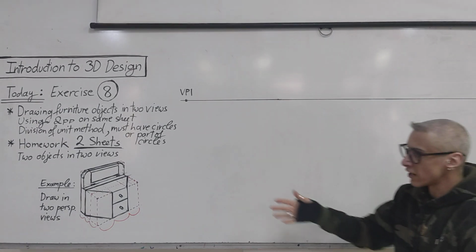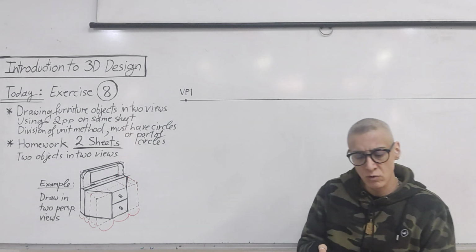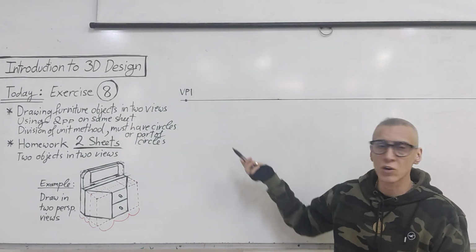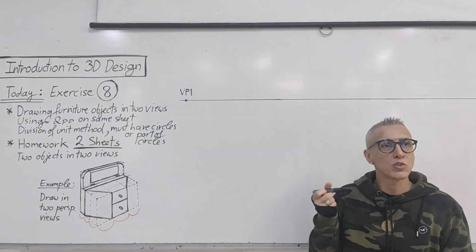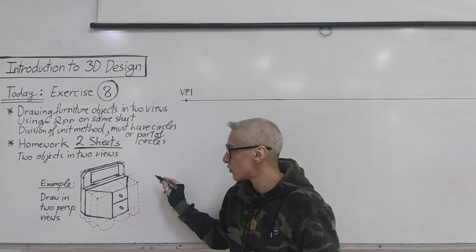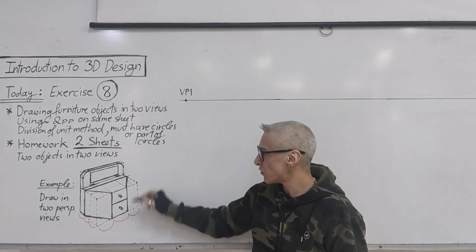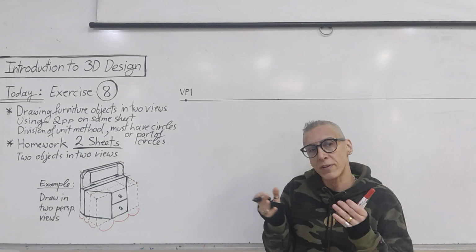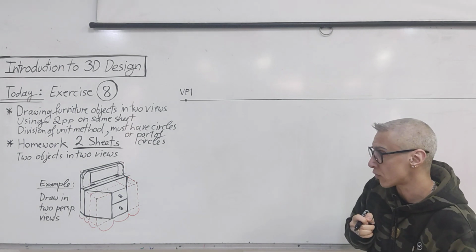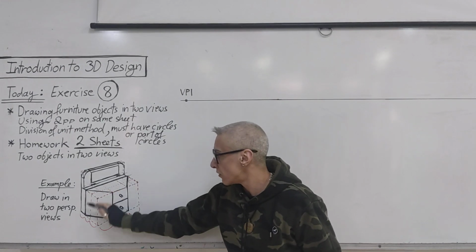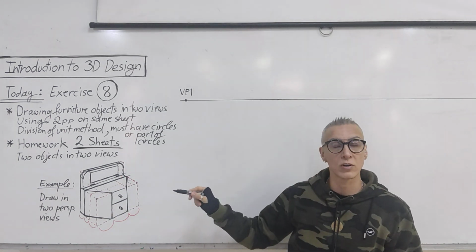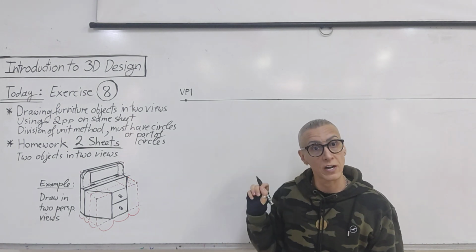Now, we will draw this very simple furniture piece and use some of the methods that we explained before. Now this, we can draw it in several ways. If I want to draw it really fast, like a very fast sketch, I will not use any method. I will just draw very fast in perspective and estimate all the areas just to understand the object. But if I want a little bit more accuracy, we will draw it a little bit more carefully, okay, using the methods. Now, I can start drawing it by drawing first the big cuboid or cube, because we always start this way.